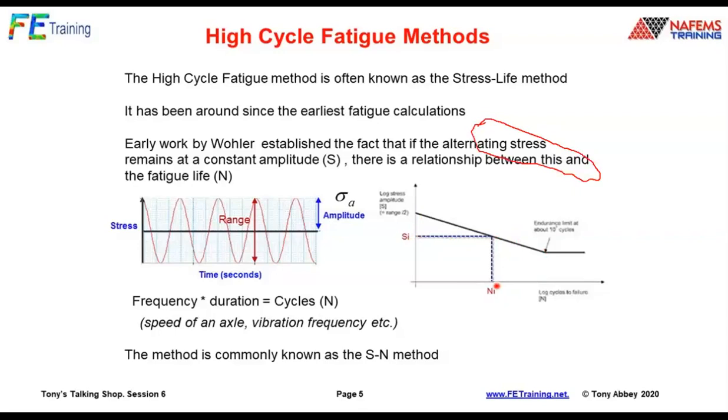Now, the number of cycles to failure is not dependent on time, like wall clock time. It's dependent on number of cycles. So I have something such as a ground-air-ground cycle event of an aircraft maybe happening every 8 hours, pressurization, depressurization, that's one cycle. My aircraft hopefully is going to last 30 years, so that's a long life. With something like a railway axle, maybe I've got to replace it every 2 years or whatever it might be. Some things get even higher usage.